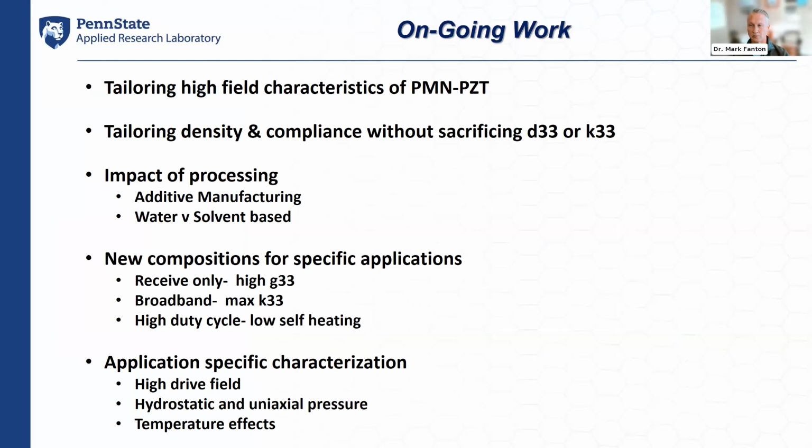Ongoing work for us here at Penn State, we're continuing to explore and try to understand and tailor the high field characteristics of the PMN-PZT phase space. Certainly for very high drive acoustic applications, that's of interest. We are actively exploring the ability to tailor density and material compliance without sacrificing d coefficients or coupling coefficients.